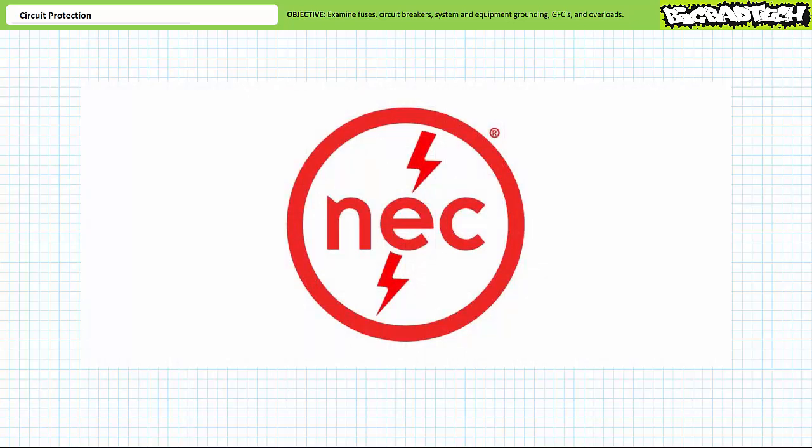The National Electrical Code is there to safeguard people and property from electrical and fire hazards. Pay attention and don't operate devices outside their intended range, nor excessively overload them for sustained periods of time. If this advice is to be boiled down into a single standing order, let it be this: watch the current. Given our understanding of the power equation, we realize that power dissipated by a device is proportional to the square of the current through it. It is therefore understandable that it is of primary importance to maintain current at or below a certain predetermined level, since any increase in current constitutes a geometric increase in power dissipation.